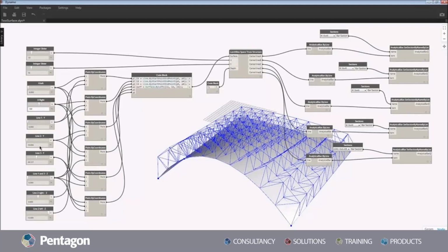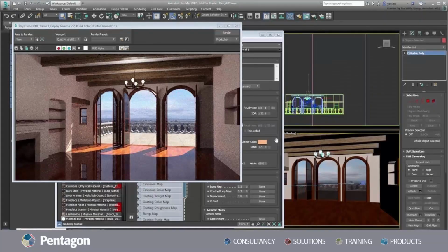And what this does is it can allow you to automate repetitive tasks. For example, creating and naming sheets. You can create a Dynamo script that might run and do 100 sheets, 200 sheets for you if you know that they're going to have the same naming convention, they're going to have the same views, or they're going to have the same setup in each one of them. You can really save a lot of time with that. You can also use it to extract information or to try out different, say you want to try out different truss methods, see which one's going to get you the most support, etc. Try out different design options.